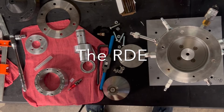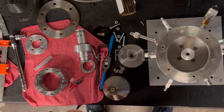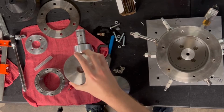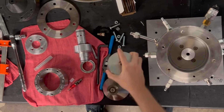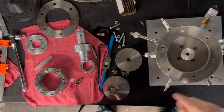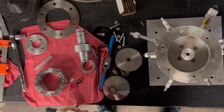So here we have the RDE that we used for our project. As you can see, we're looking at it from a top-down view, so you can see into the chamber. Right now, it's missing the inner wall, which is this piece right here, but you can imagine that's slotted right in the middle there. Around the outside, you have a number of things. These three are pressure transducers. That's what we're using to track the pressure wave as it goes around the chamber.